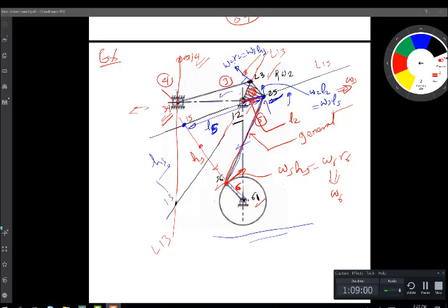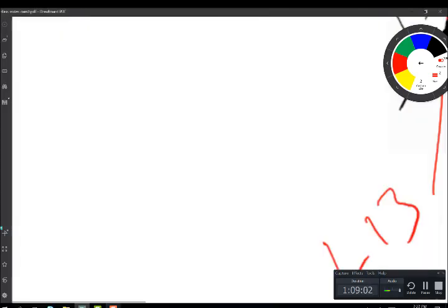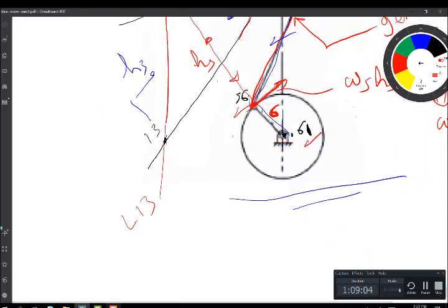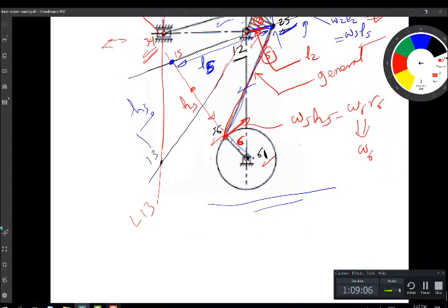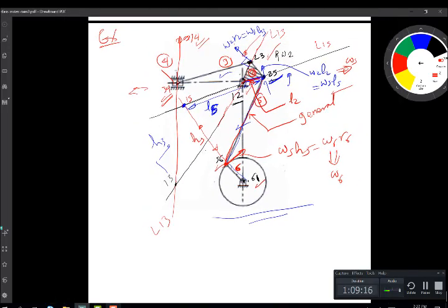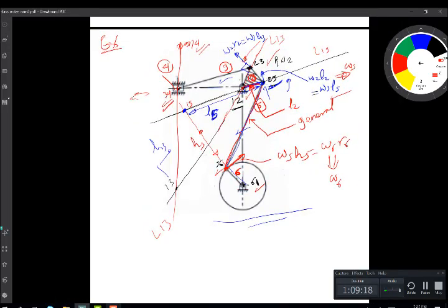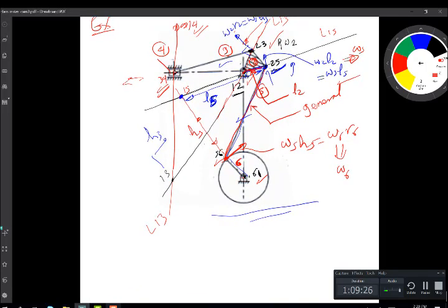Okay, so now this is possibly the end of the velocity analysis. And in general, we looked at how to do velocity analysis with equations by differentiating the loop closure equation. And then I also wanted to give you this insight in terms of the velocity pole and the nature of motion in a plane, a topic which links nicely into velocity analysis.